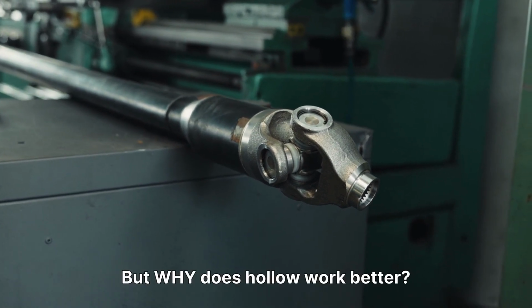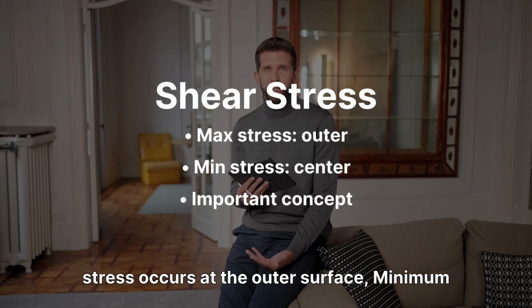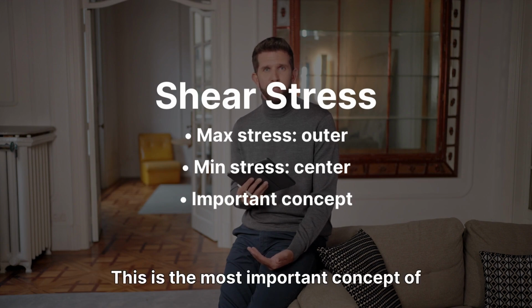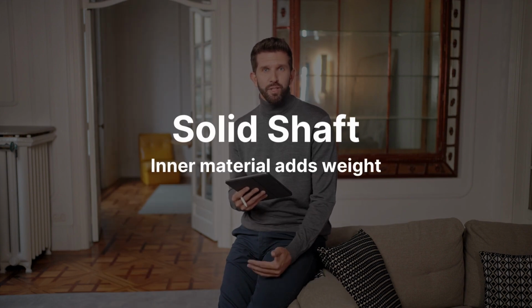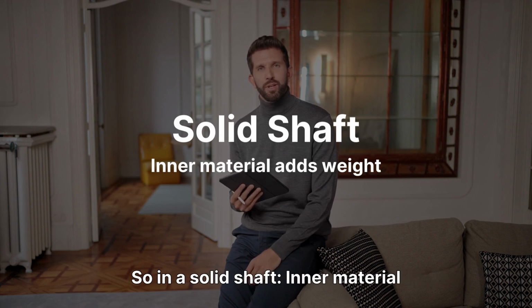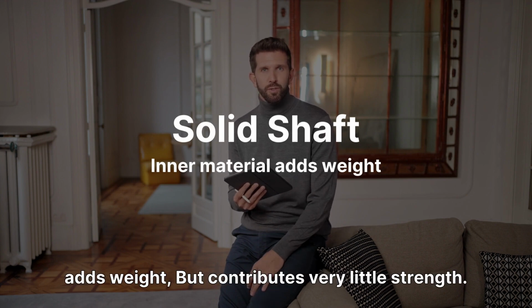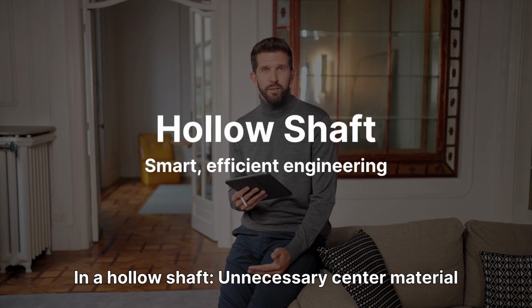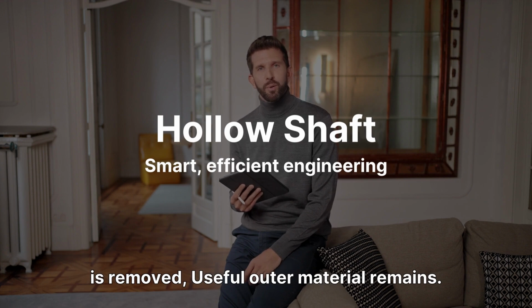But why does hollow work better? When a shaft transmits torque, maximum shear stress occurs at the outer surface, minimum stress occurs at the center. This is the most important concept of this video. The material at the center of the shaft contributes very little to torque resistance. So in a solid shaft, inner material adds weight, but contributes very little strength. In a hollow shaft, unnecessary center material is removed, useful outer material remains.